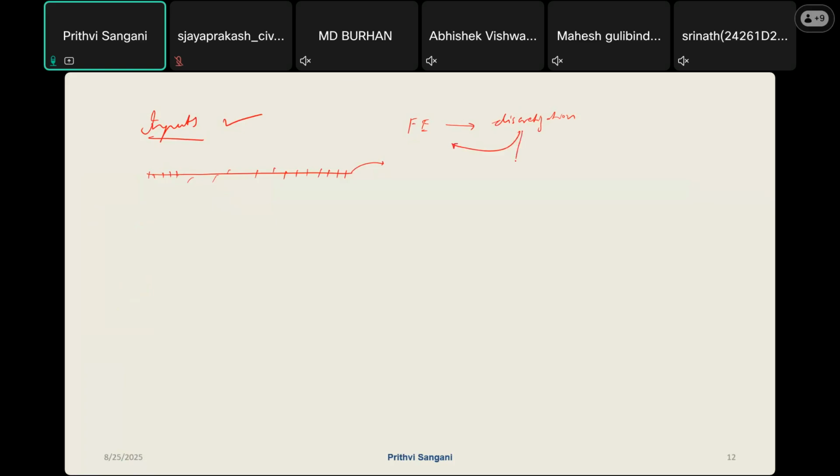For discretization, like I mentioned, let us say in the previous example you have given the cross section. You also know the span length. Now there is something called meshing. In meshing, let us say the length of the beam is 1000 mm, which is 1 meter. In meshing, you can say that I want this beam to be discretized into say 10 parts, 30 parts, 40 parts, 100 parts, whatever you wish.